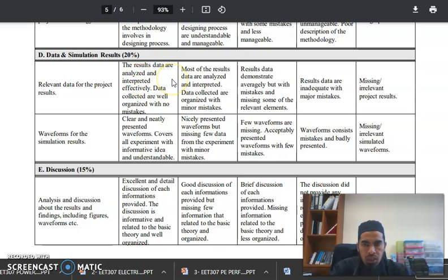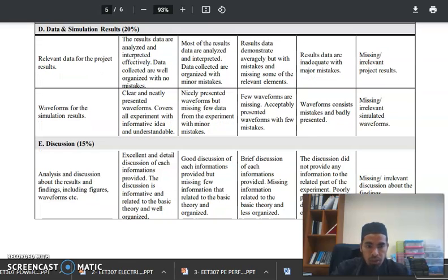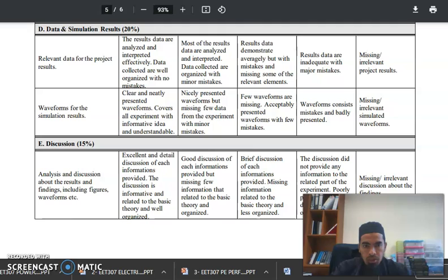Do not lump all the graphs and curves on one screen, because voltage, current, and power represent different values and units. Present them clearly, with at least 2 cycles in duration. It cannot be too long, because you cannot distinguish the curve, and it cannot be too short, such as half a cycle or 1 cycle only, because it's too narrow.